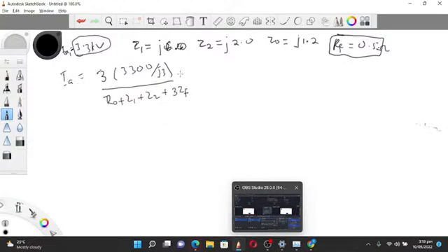Very, very simple. So the first question asks for the fault current, and you can just find it from here. This will be 3 times 3300 over root 3, all over the sum of the impedances. You put your impedances there, J6, and so on. These are all reactances, so you combine them and we have 9.2, plus there's a resistance, but we need 3 times that value, so that's 3 times 0.5.